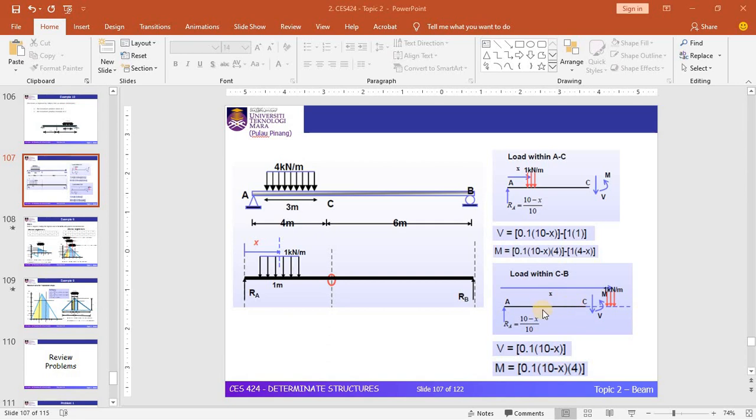The basic principle of ILD from the previous examples still remains the same, but here you need to be careful with the load applied. If the question considers point loads, you need to apply a 1 kN point load. If your load is a UDL, you need to apply a unit UDL load.